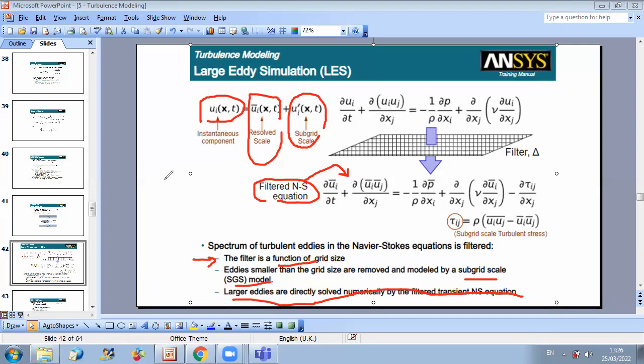Whereas whenever you develop turbulence models, you will have certain error, okay? And you have to develop several models to be able to approach the problem and have as high accuracy as possible. So by using large eddy simulation, you can guarantee that for large eddies regions, you have a very good prediction of the flow behavior. And then for just small eddies regions, you can treat them by the turbulence models you developed before. So this is mainly the idea of large eddy simulation.